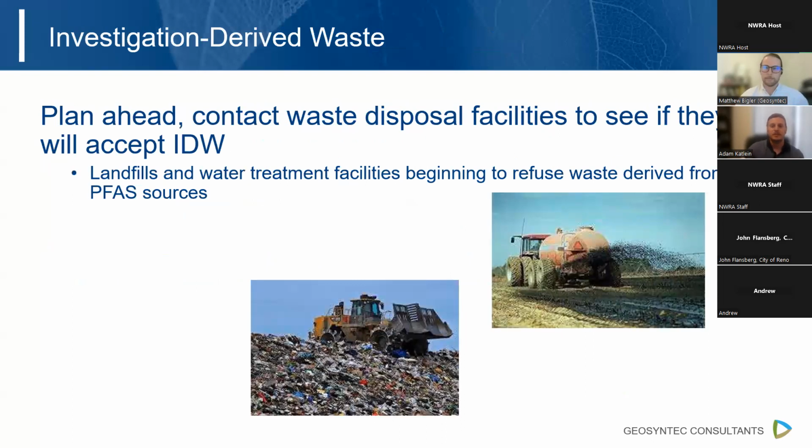Next. Another note, also for investigation-derived waste, IDW, is to plan ahead and contact waste disposal facilities to see if they will accept whatever IDW you are generating. We've seen some reports around the country of landfills and water treatment facilities beginning to refuse waste derived from PFAS sources. This has a lot to do with the changing regulation out there with how any waste or generated materials are being regulated. So people are kind of leery about taking those wastes into their facilities.